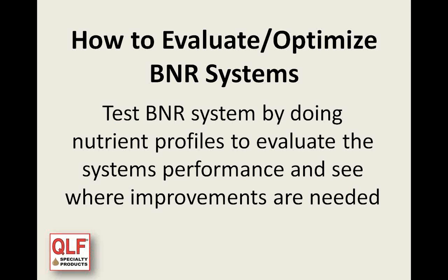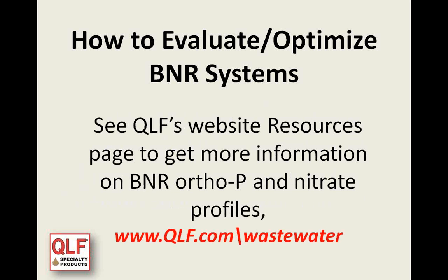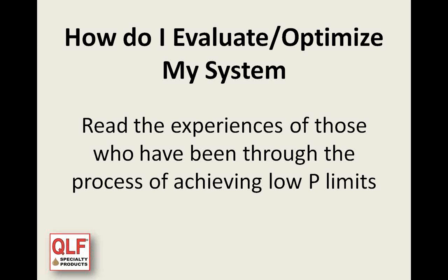Another way to optimize your system is to test the EBNR system using what's called nutrient profiles to evaluate the performance of the system and to see where improvements can be made. It gives you clues to where your problems are. Again, there's more information about profiles on our website.